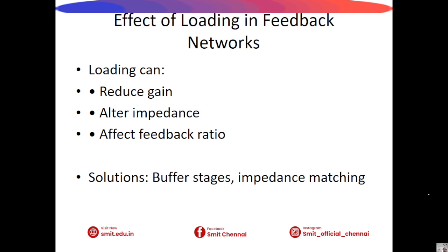Loading can cause reduction in gain, changes in input and output impedance values, and variation in the intended feedback factor. As a result, circuit performance may differ from theoretical calculations. To minimize loading effects, engineers often use buffer amplifiers, impedance matching techniques, and high input impedance devices.